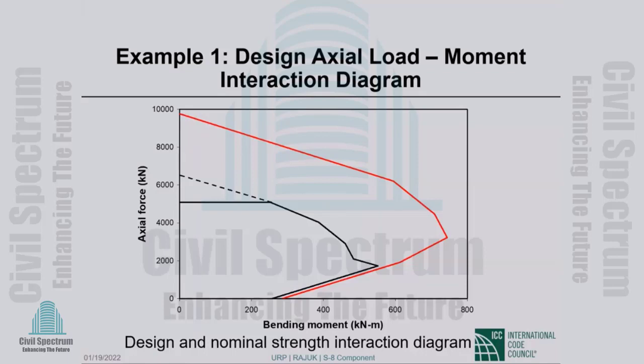The second thing, top bar versus other than top bar. Top bar versus other than top bar is for horizontal members, not for vertical members. People have used it in walls and things. I personally do not believe that it is meant to apply to vertical bars in walls or columns. So don't worry about top bar effect when you are splicing column bars. That simply does not apply.